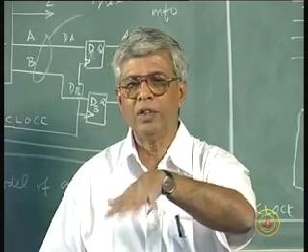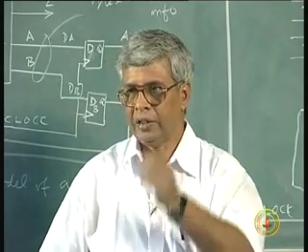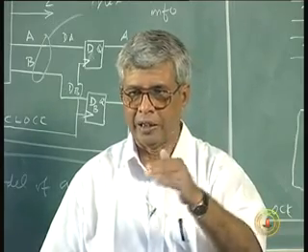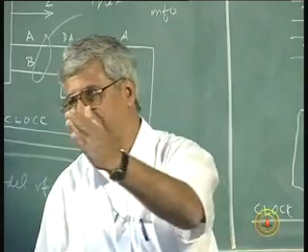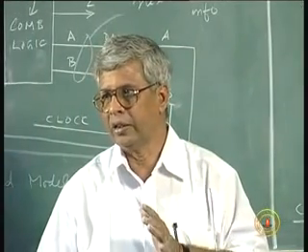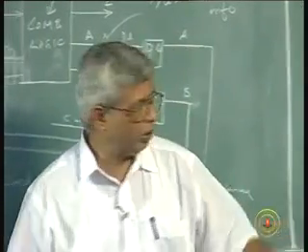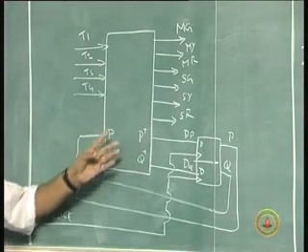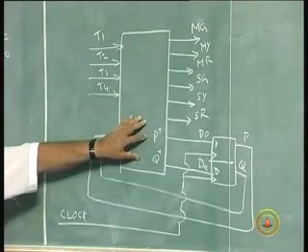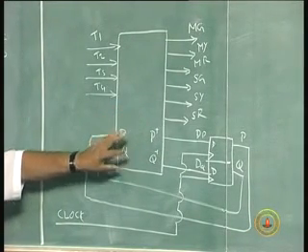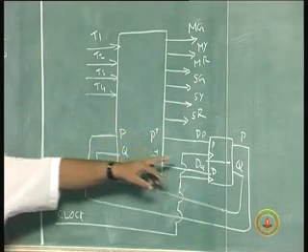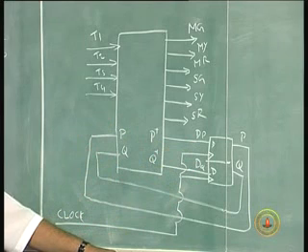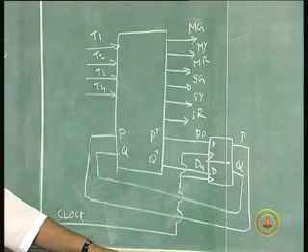So first we will start with synchronous sequential circuits, wherein there will be a clock and always you can rely on the clock to work at clockwork precision. At the clock transition, the system will change its state. So all you have to do is to make sure that the new input values are put here before the next clock pulse arrives. You take all the time in the world to determine the combinational logic delay, because it is not going to do anything until the clock arrives. Then only it can go to the next state. So we will see many examples in the coming classes.